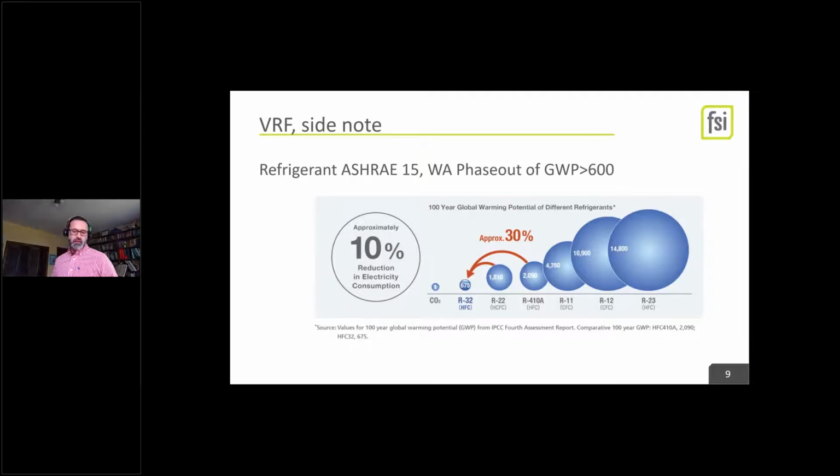Yeah, good question. So we're in an interesting code environment right now. Seattle has an all electric requirement. So if you're touching a system in Chapter 5 as an alteration, and again, if you're doing something more than an emergency repair, you are gonna move it to heat pumps in Seattle. Right now, the 2018 codes for Washington do not have that requirement. You can keep your gas heating, again, with the caveat that the energy use intensity targets, the energy use per square foot per year targets of the building energy performance standards are going to continue to ratchet down.